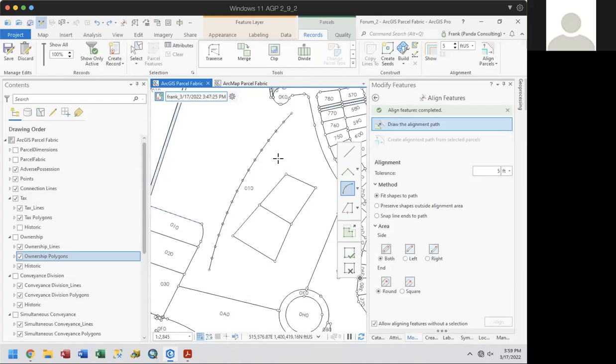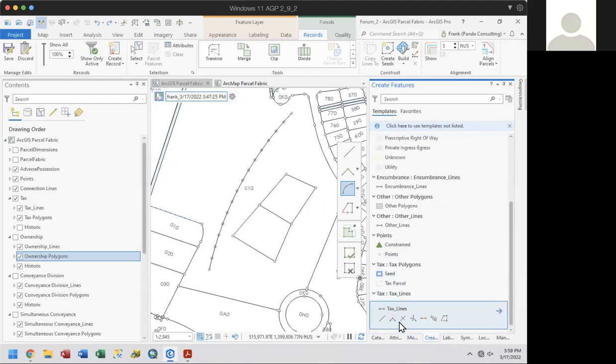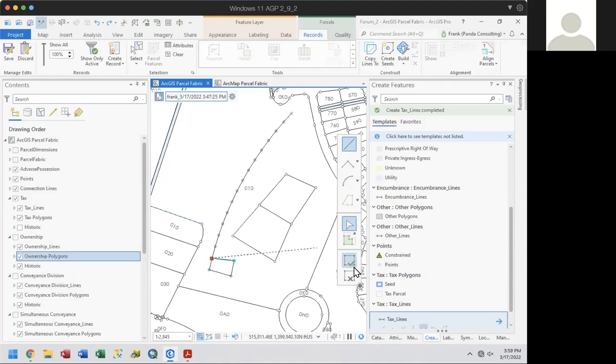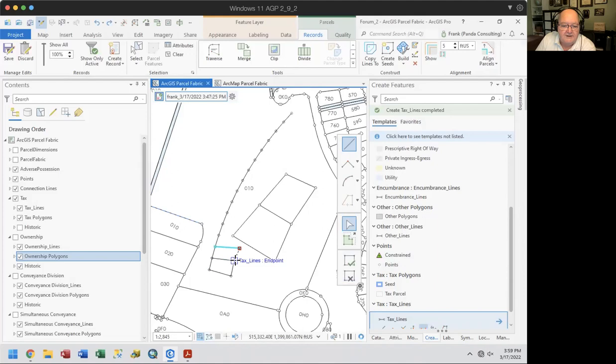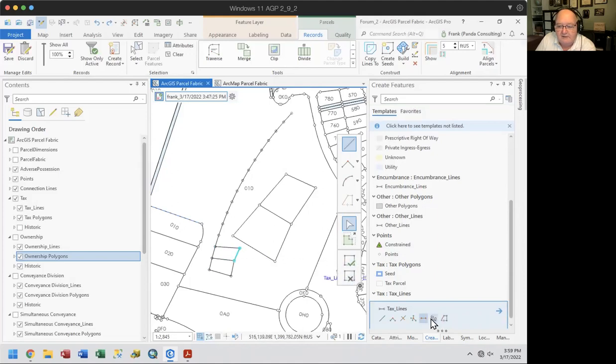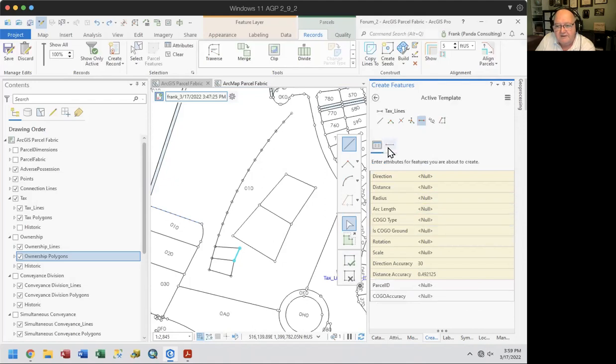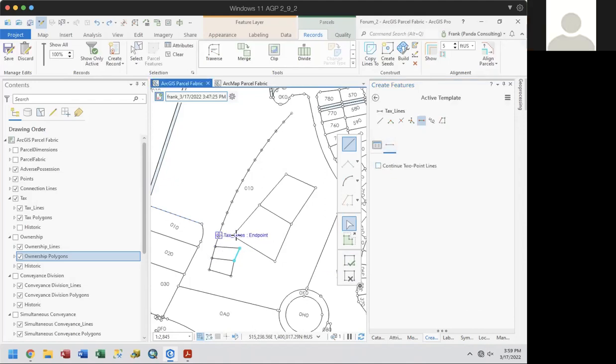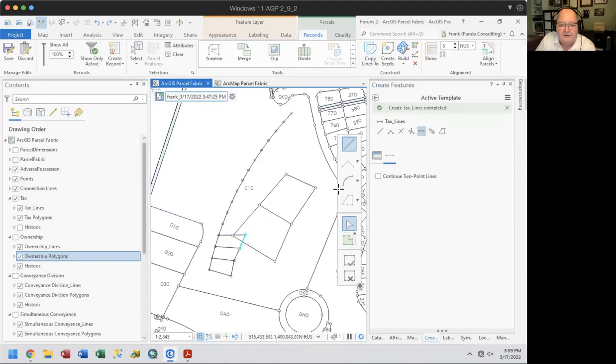Say your first segment down there is lot 1, right? Can you build lot 1, not build parcels or create seeds, and then build lot 2? Can you then align those 2 and then go to lot 3 and align it with 2? Sure, I don't see any reason why you couldn't. I don't know if it'll help, but that was just a thought. Align every single one while you're building it. Yeah, I agree. Let's see if we can demonstrate this.